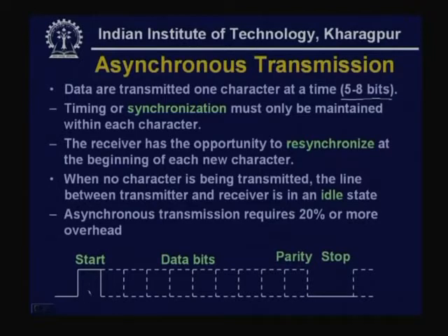With the help of a start bit, the synchronization is achieved, and this signifies the beginning of a character, and after that there can be data bits which can vary from 5 to 8, and there is an optional parity bit.